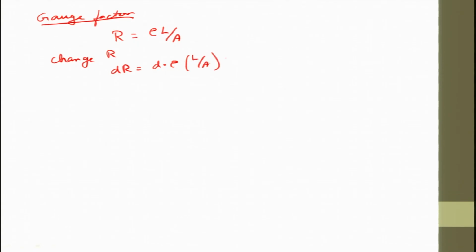From there, we have to now find out something called a gauge factor. So, we know R equal to rho into L by A. When there is a change in resistance, we basically start differentiating: dR equal to d of (rho L by A). Now when we try to expand,